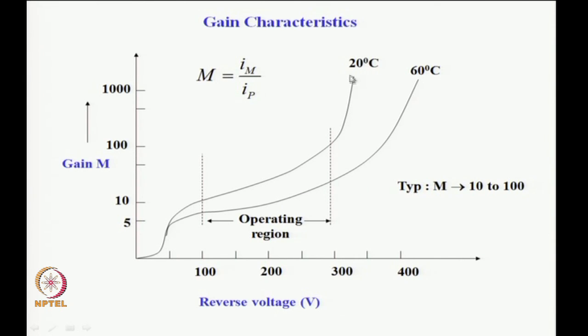So, this is just an example to show that it is temperature sensitive, and the higher the temperature, the lower the current gain. In fact, most of these detectors are cooled. One can cool this further, and the curve would qualitatively look like this. The characteristic will go up if you cool the detector further, and it will be less noisy as well.